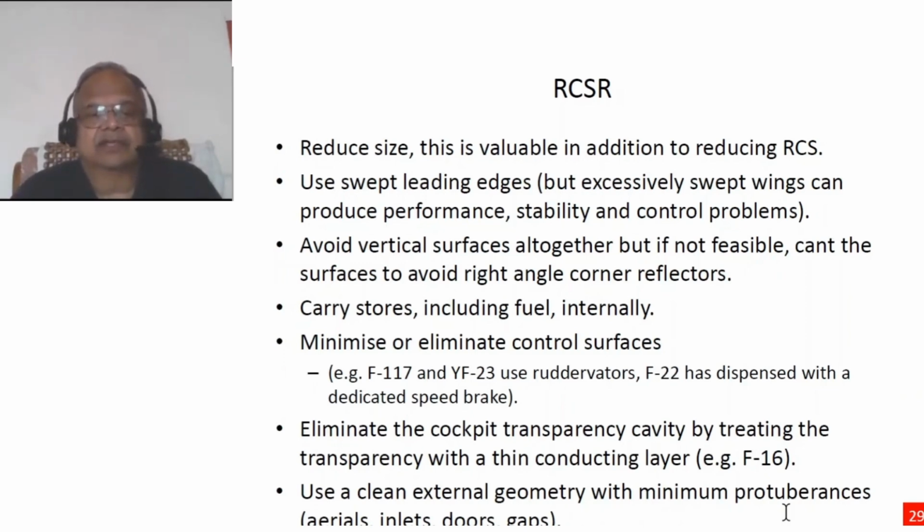The other technique is to avoid vertical surfaces altogether, but if not feasible, cant them so that the surfaces avoid right-angle corners, the kind of thing you saw in the F-16, or even now in the Sukhoi, you can see the same thing.